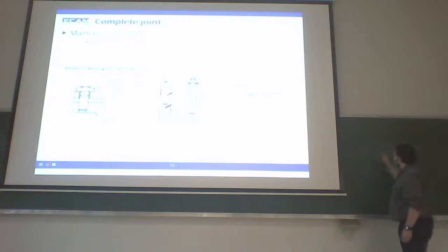You will close this part to be like this by a screw in the middle, plus a nut or a screw inside a threaded hole. Here it's a screw inside a threaded hole. So by reducing the space, we'll exert an effort, concentric effort all around the part number 2 in the middle, the yellow one here, to maintain the position between the blue one and the yellow one.